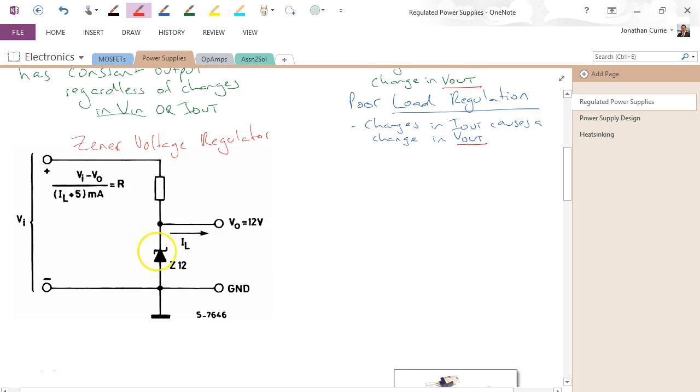Now, we all know with a Zener voltage we're going to have a voltage when connected in reverse bias that is fixed when looking in parallel with that device. So the voltage across that Zener will be fixed once it exceeds it, within operating specifications of that Zener.